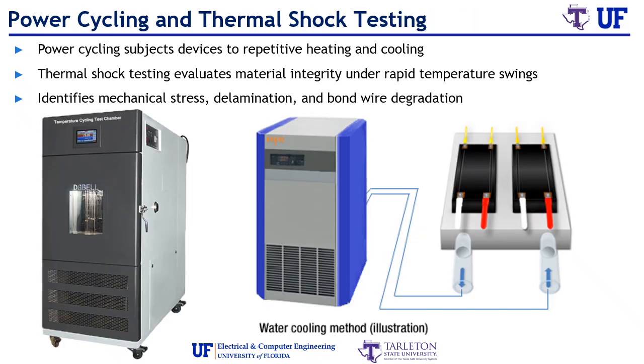Power cycling repeatedly heats and cools devices to test material fatigue and long-term stability. Thermal shock testing exposes components to sudden temperature changes, identifying weaknesses like cracks or delamination. Specialized test chambers maintain strict thermal control, ensuring accurate, repeatable results that reflect real-world conditions.